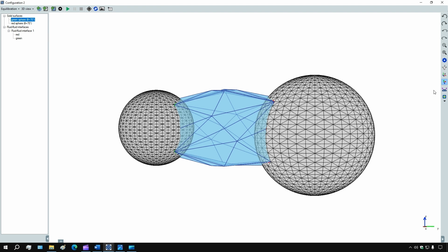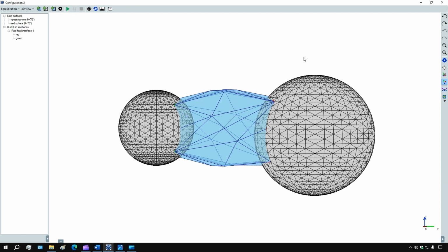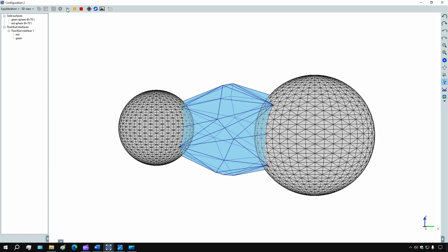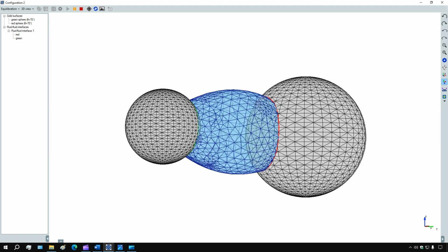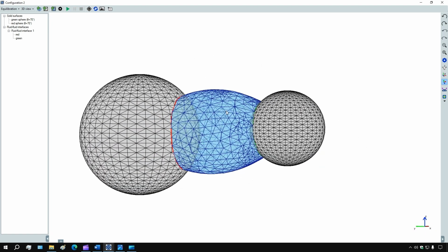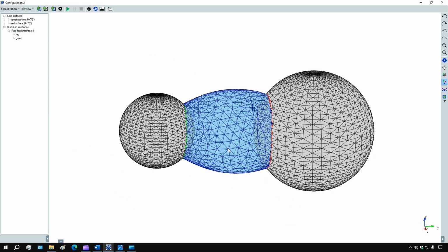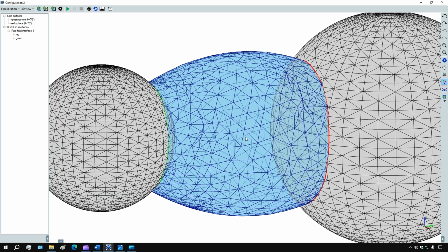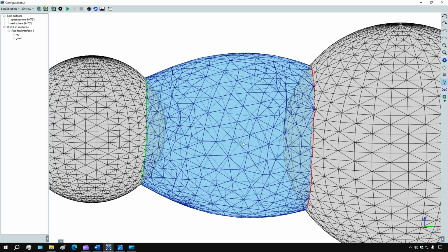The fluid below the interface is the fluid inside the capillary bridge, as indicated by the normal vectors. So the contact angle of 70 degrees is expected inside the capillary bridge. Let's then start the equilibration. We have now computed the equilibrium shape of the capillary bridge between the two spheres, with a contact angle of 70 degrees. By following an analogous procedure, we can easily simulate the equilibrium shape of droplets and capillary bridges with any topology, and wetting solid surfaces with any geometry.